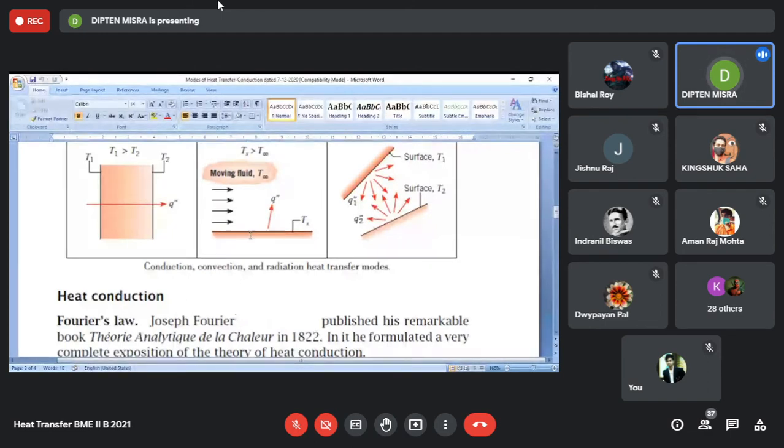So even if it is a convecting fluid, at y equal to 0 plus, there will be a fluid particle that will be stationary because of a phenomenon known as the no-slip phenomenon that arises due to the viscosity of the fluid. If the fluid is a viscous one, then because of viscosity, a very thin layer will be sticking on the wall.